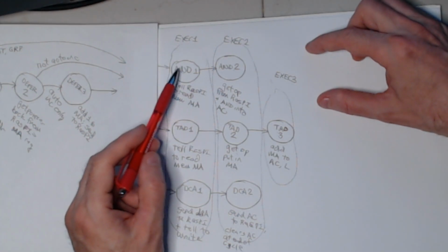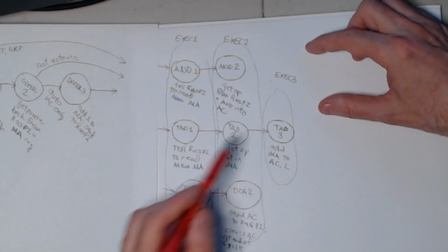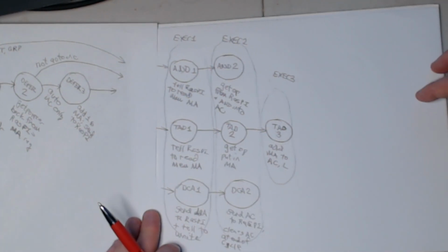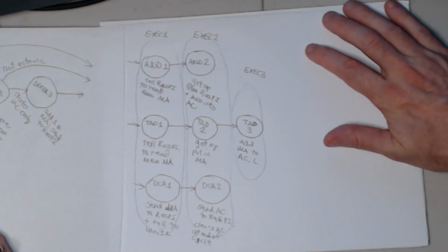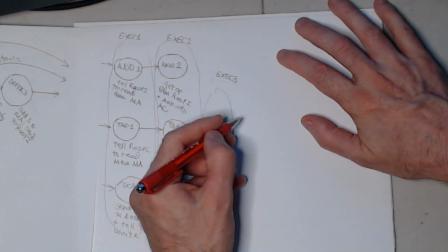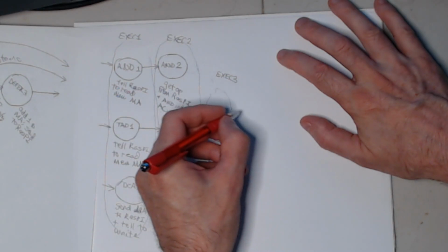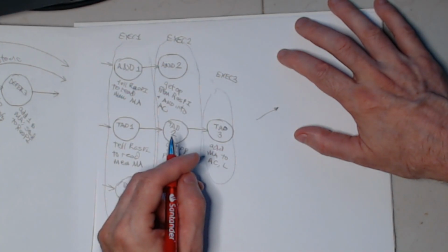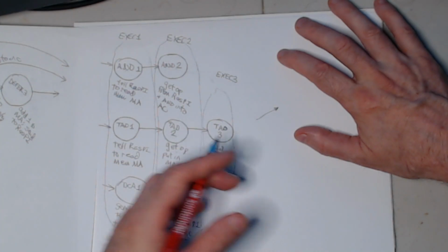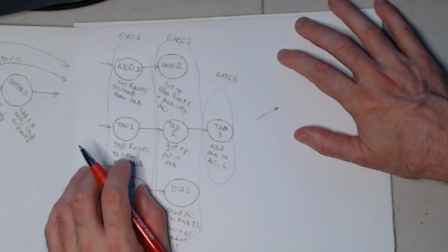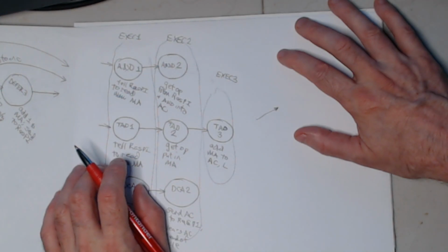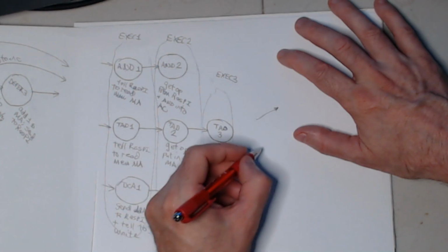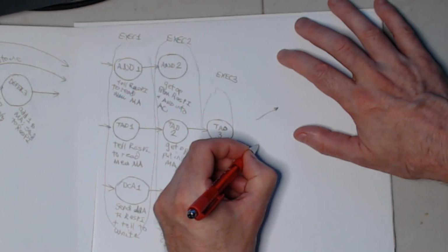Okay, now assuming that it's finished, whichever it is, AND 2 or TAD 3 or DCA 2 or whatever, now it's got to go back to process the next instruction. So it's going to check the interrupt request line. The Raspberry Pi simulates all the I/O devices, and it pretends it's the disk controller and terminal controller and all that stuff, and so it has an interrupt request line coming out of it, just like you would expect on any I/O bus.